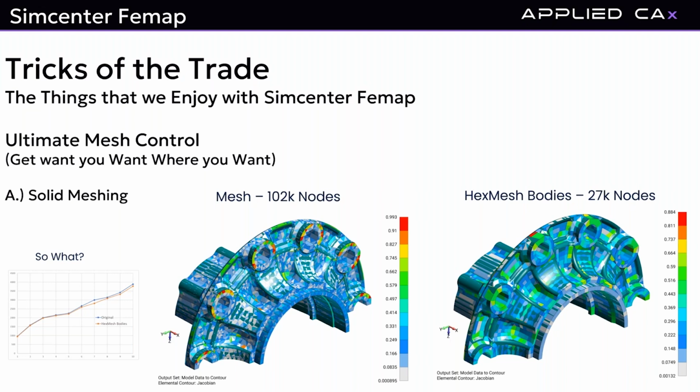Of course, with solid elements it's 3 dimensions. A high number in Femap means the Jacobian really has to work a lot; the element is highly distorted. If you've been working a while, you probably know that anything above 0.9 for a tetrahedral, Nastran won't run. It'll kick out an error message. If you slow down and poke around and look at that element, you'll go, oh my God, what a piece of junk.